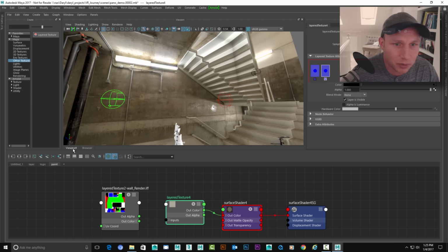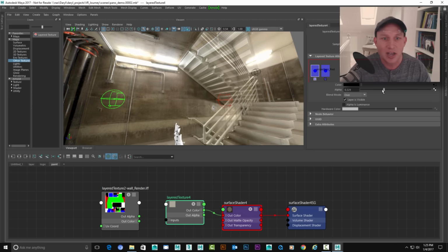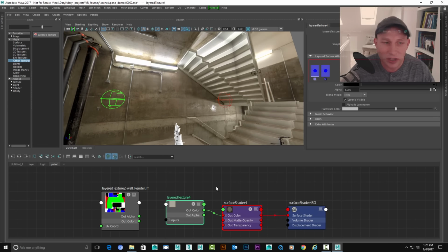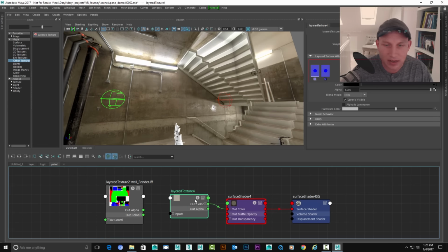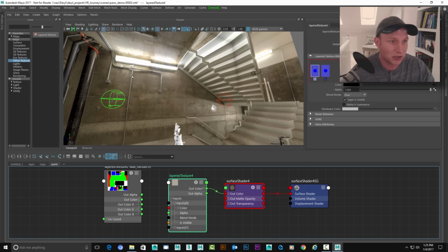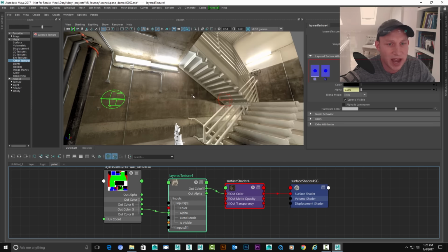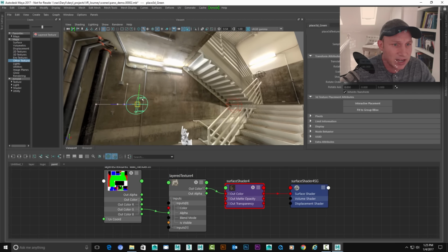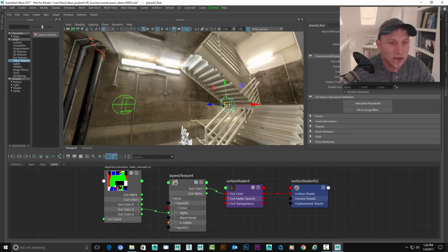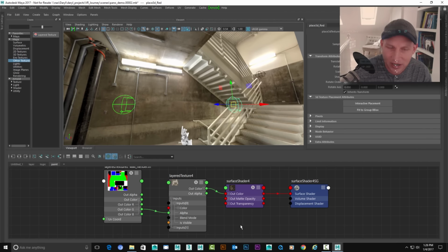So now if we jump back to the viewport, and we go back to our green projection and we start to drop that alpha channel down, you can see we're transitioning from one projection to the next projection. Now we want to use that matte file to generate the alpha channel, right? So all we're going to do is expand out our inputs, and we're going to go to input 0, which is going to be our green input, and we're going to grab the out green and shove that into the alpha. So as soon as we do that, you can now see that we've got this guy covering everywhere there's green, and then we've got the second node in our layered shader covering everything else. Pretty straightforward, right? Very easy to do.